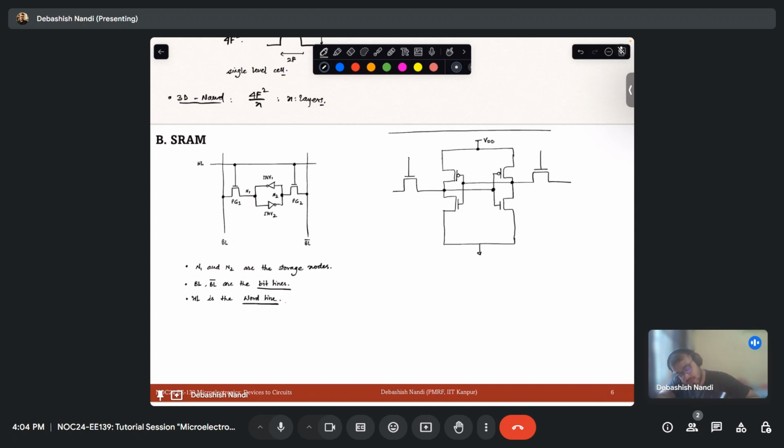So you have your word line flowing down here. Always note that your word lines are connected to the gates of the transistors, that is basically it controls the on and off operation of the transistors. And if this is your word line, these are the bit lines. So this is your BL, this is your BL bar.